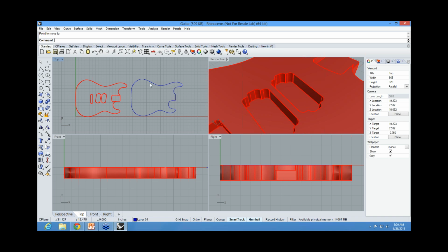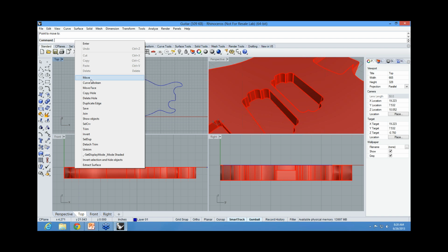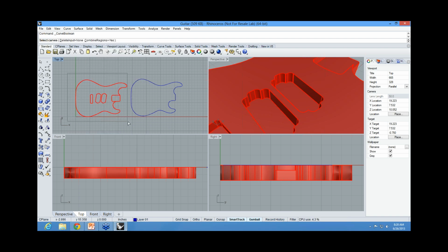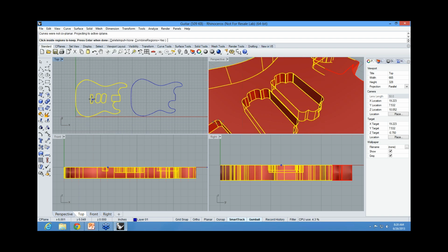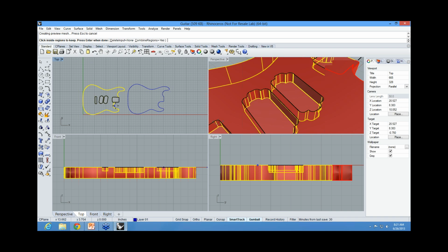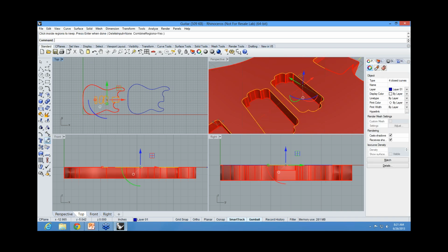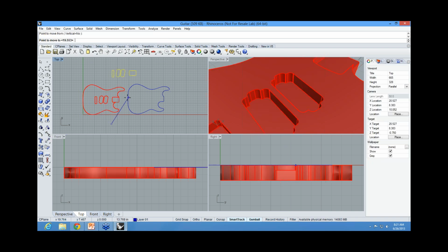so that you can see that I can get that outline. And that's a nicely cleaned up duplicate of that outside edge, right? I didn't have to take a section. There's a lot of other ways I could try to capture that edge, but this is the quickest way to do it. Nice part about curve Boolean is if I want to take another set of curves off here, let's say that I want all the pocket outlines, I would just grab it and click in each pocket. And what it'll create is a set of pockets for me.